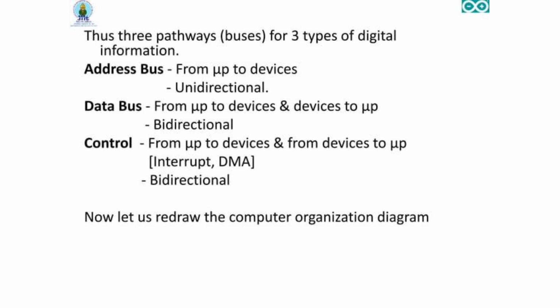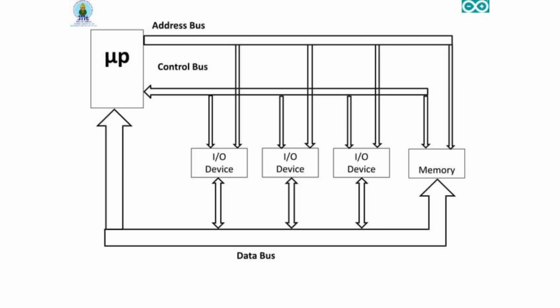And to pass the data between these blocks, we must rely on the bus architecture. A bus is defined as a highly synchronized pathway for the rapid transfer of digital information between different units. So when a processor performs a write operation to update the memory or command an output, it coordinates three things simultaneously. It outputs the physical location through the address bus, places the actual binary data into the data bus, and then executes the pulse over the write control signal.